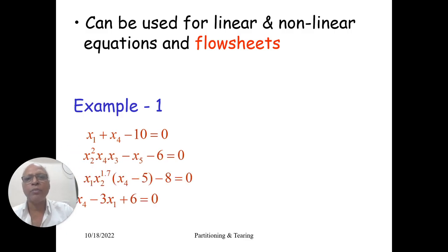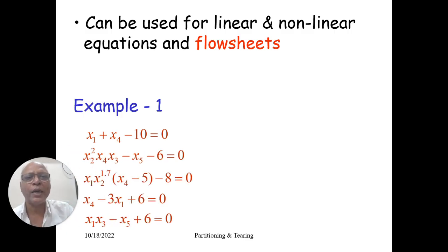So the algorithm that we are looking at can be used to partition equations or even flow sheets. The equations can be linear or non-linear. For example, consider these 5 equations in 5 unknowns, x1 to x5. There are 5 equations. So we are not going into the solution process. We are only trying to address how to partition these equations. So should we solve all these 5 equations for calculating the 5 unknowns as one single problem, or is it possible to divide this problem into subparts? That is what is meant by partitioning.